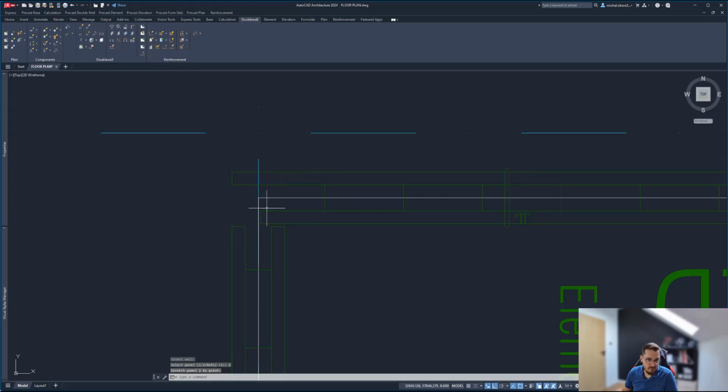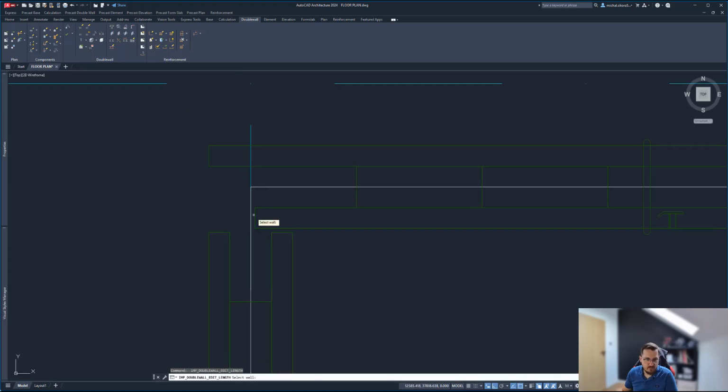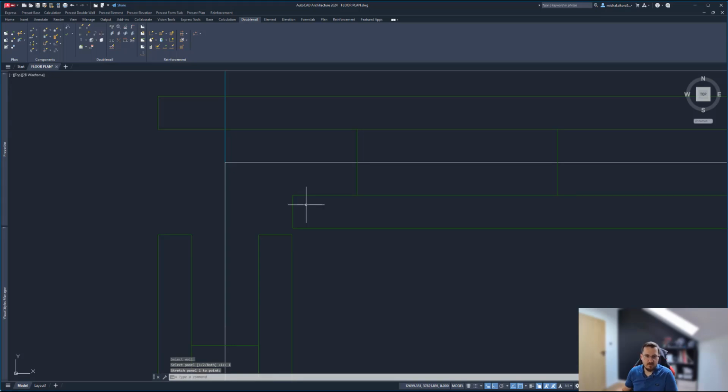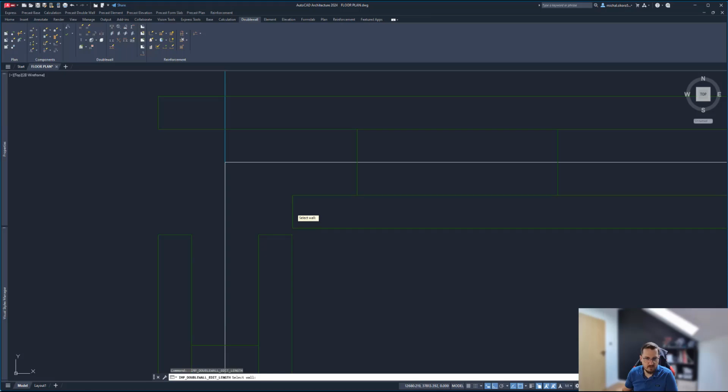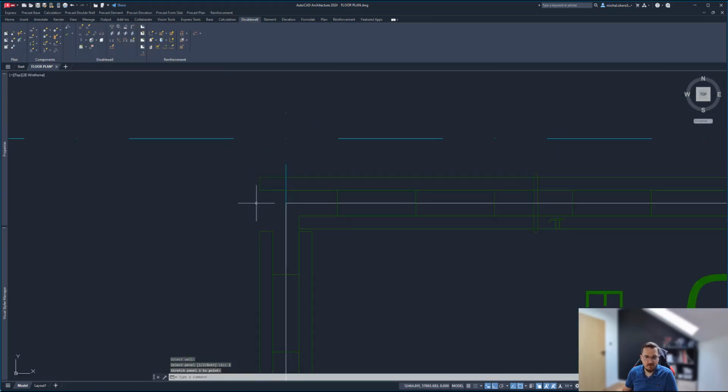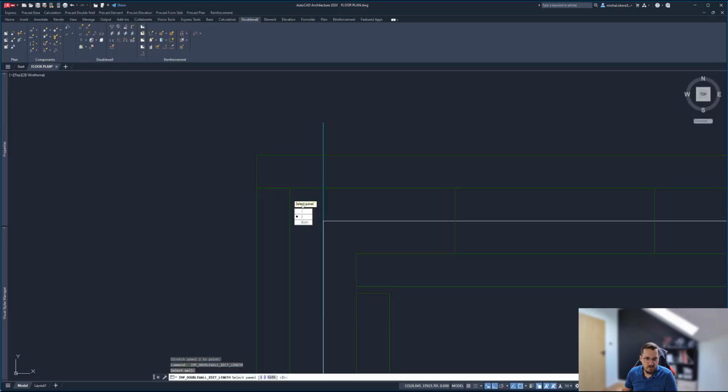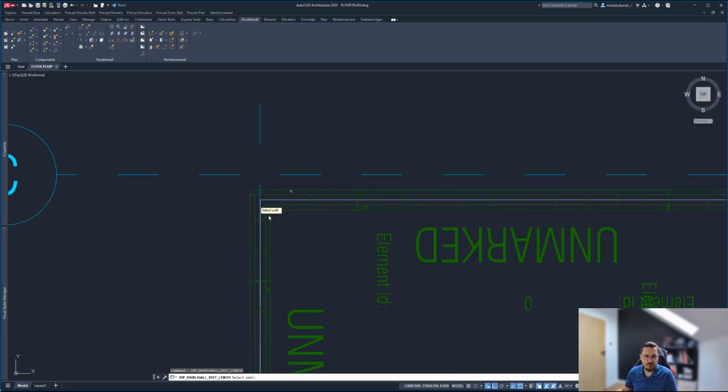So that's good. What I'll do now, I'll just extend the second panel, so this one, and I'll move here. And I just moved one panel. What I'll do here, I'll move now this panel. So this panel 1, move it to here. Oops, I wasn't supposed to do that. I was supposed to select this one and actually move it just to this edge. Yes, so that's good. And now just this one, like that, and move that by 10 mil back. And now we have a nice little connection.